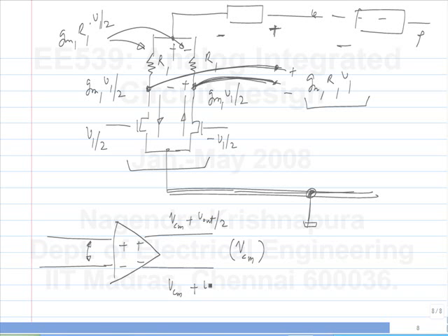If you think of it as an ideal op-amp, sorry, this is minus. So this is the alternative to something like this. In the ideal case, you can assume VCM to be 0, just for simplicity. In reality, it will be some bias value. So the two outputs will be forced to go equally in magnitude, but opposite in direction. So this is a fully differential op-amp.